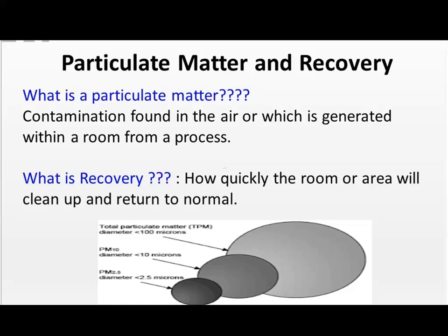We know we have a process where we're dumping bags of powdered raw materials into a tank. Obviously, that is going to generate quite a few particles, but we want to know that in everyday operation those HEPA filters are capable of removing those particles quickly from the manufacturing area. We know that they're capable of removing particles as small as 0.3 microns, so we want to make sure that they are remaining efficient. So we're looking at how quickly the room recovers and returns to normal operation.